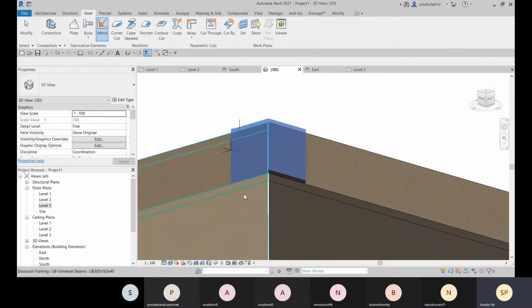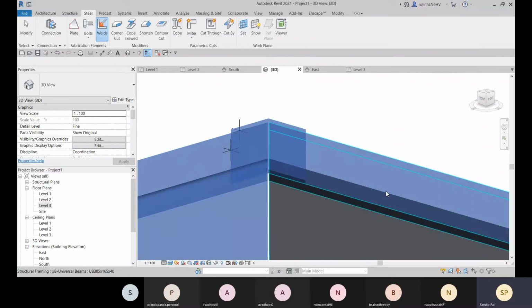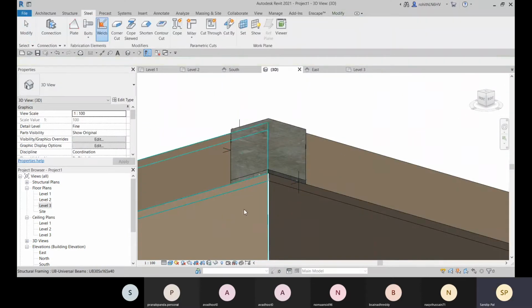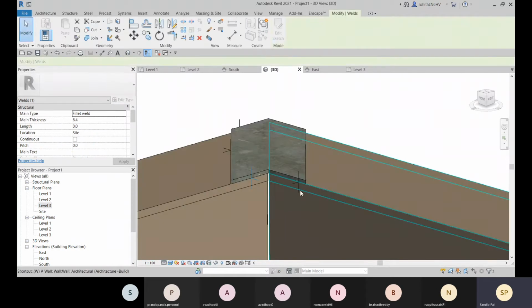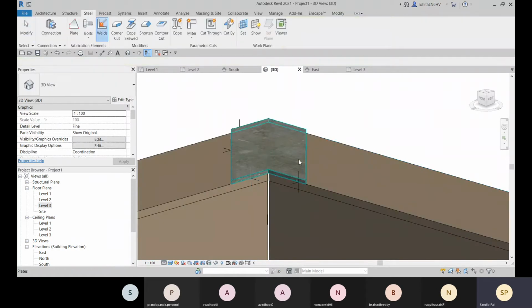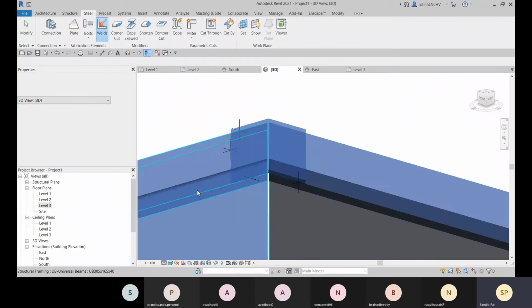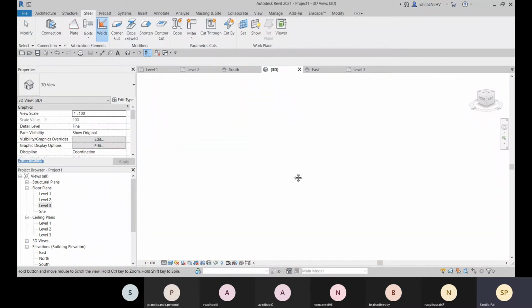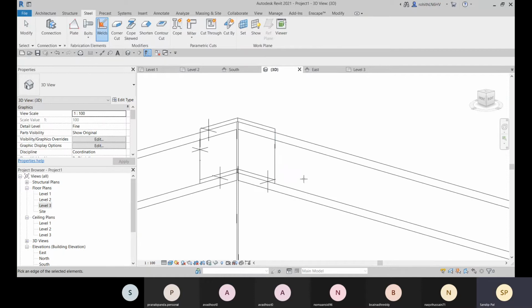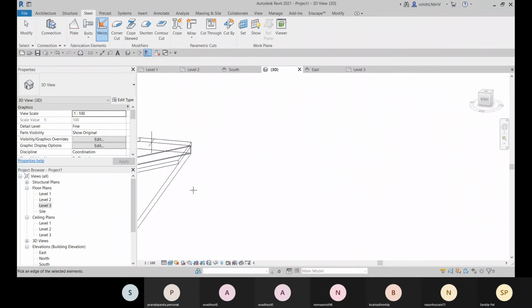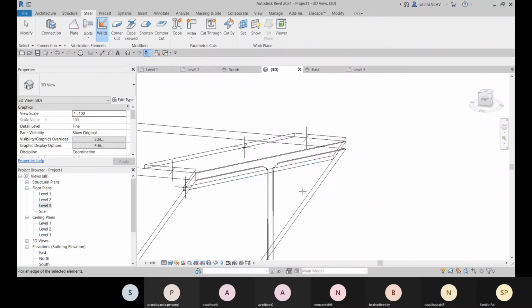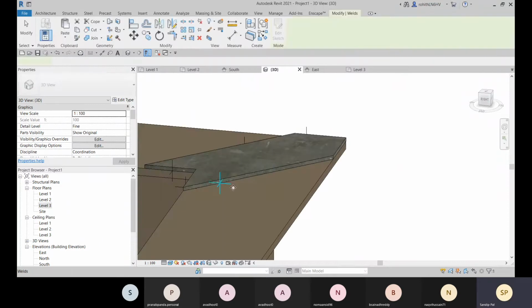Okay. And now I'll select this one and this one and this one, and then press enter, and then select the edges, WW. Select this one, holding control, select the others, press enter, then select the edge, WW as the shortcut, and then select this one, holding control, select this and enter, and select the edges. So don't select the upper edges. Select this edge, and that is done.